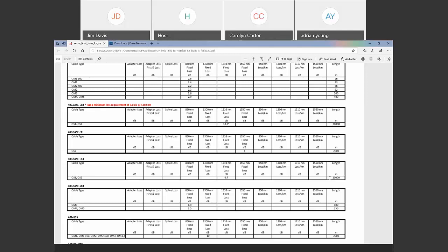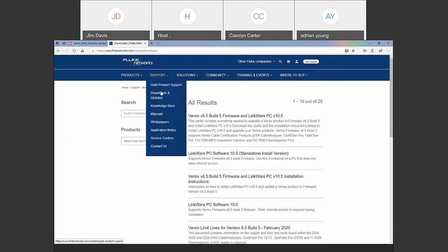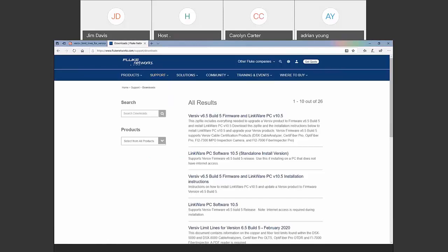The 500 represents the new generation of transceivers designed for data centers, and that's probably not what we're talking about here, because they're talking about the backbone here. So you're probably looking at a 2-kilometer version. So we can run down this list, but what we wanted to highlight here is that there's a single place document where you can actually look up all these loss values. Now, this list is not fully complete because there are a lot of proprietary solutions out there, but you should be able to get to that answer from this download.